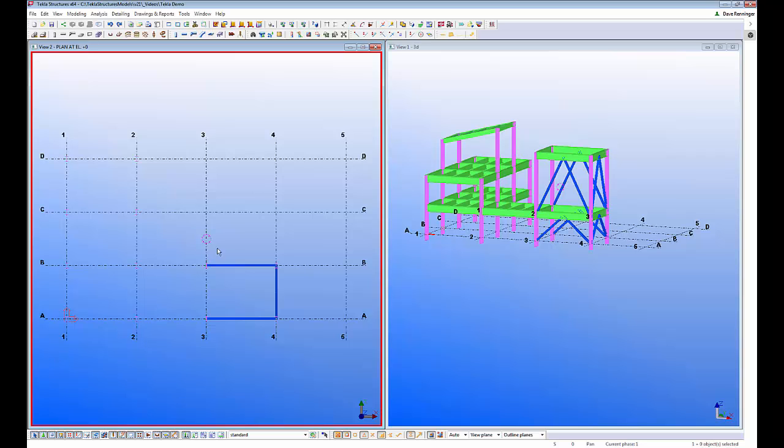All right, so I've already opened up my Plane Elevation Zero here, just to make it easier for me to model in the parts I'm looking for, just another view inside the model. What we're going to do is start by modeling in some concrete piers and pad footings along column lines 1 and 2. To model in the concrete piers, we're going to use our concrete column tool.